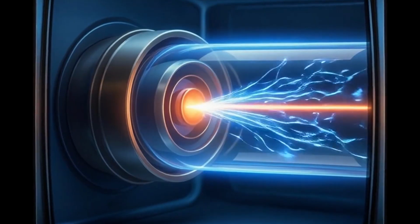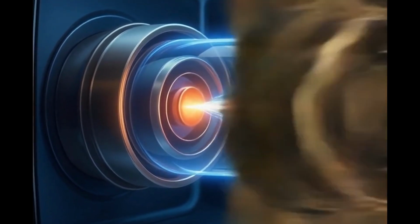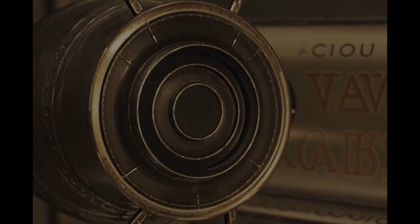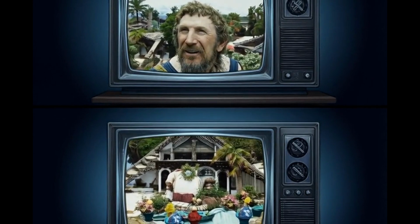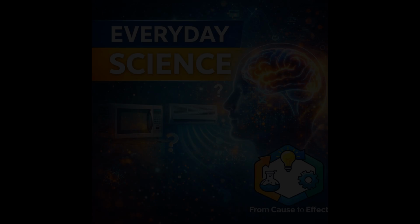A cathode ray tube relies on a vacuum to allow electrons to travel unimpeded from an electron gun to a phosphor-coated screen. Without this sealed environment, air molecules would scatter the beam and prevent image formation. The tension lies in how invisible particles create visible light through controlled collisions within a fragile glass envelope.